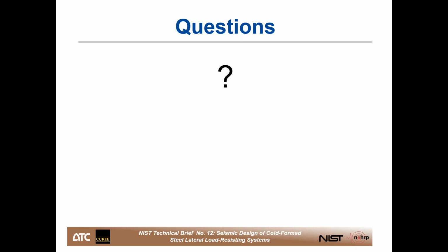Yeah, so I have seen a number of buildings that have used CMU shear walls at elevator and stair core areas. So, like long skinny buildings that may have a core in the middle and on each end, for example, where the load bearing structure might be CFS and the core material was CMU. I've also seen very similar buildings, but with cast-in-place concrete cores. And I have from time to time seen buildings that may even be a hybrid, where, for example, the upper floors use CFS lateral force resisting system elements like a shear wall or a strap brace wall, but lower down in the building, they might be, say, a structural concentric braced frame or something like that.